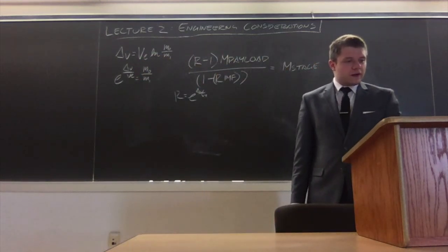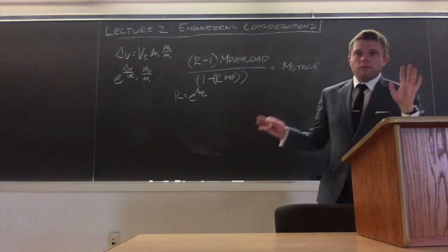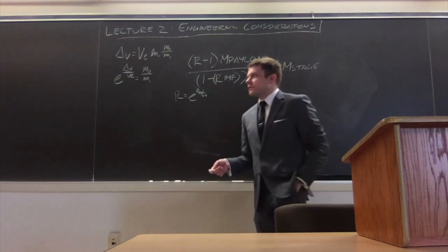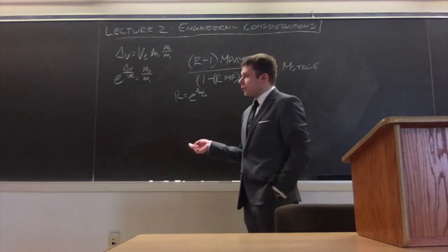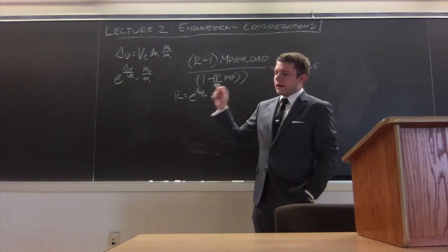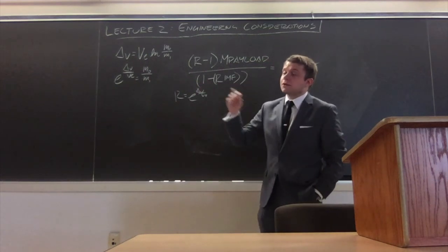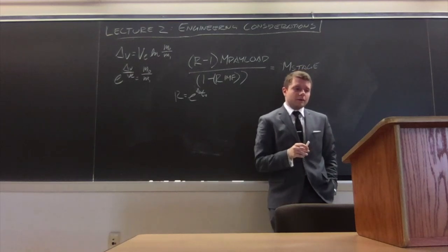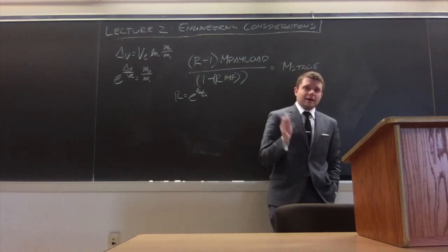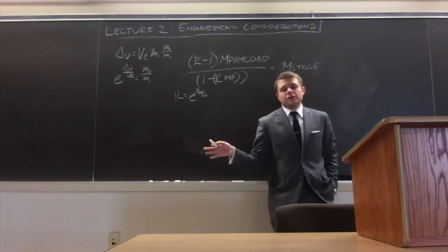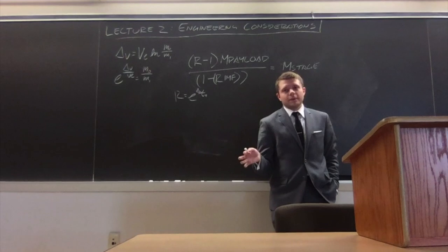So the question, of course, then is, what do we do with this? We got our delta V. I talked a little bit about the delta V in the previous lecture, about delta V getting to low Earth orbit. But what do we actually do with this? How do we go from that to that? How do we partition our delta V? That's a very technical term, but that's exactly the word that we use, partitioning. Because we can't reach space in a single stage. Actually, I put a big asterisk on that. There are conditions in which you can do it.